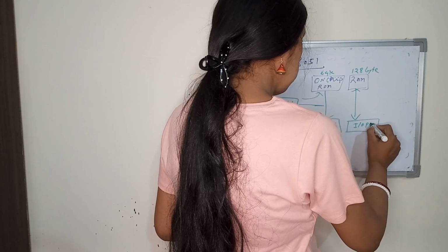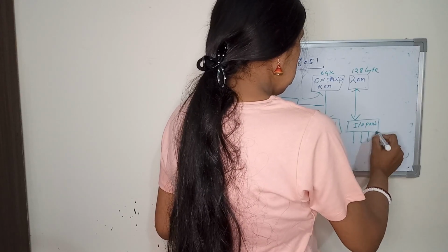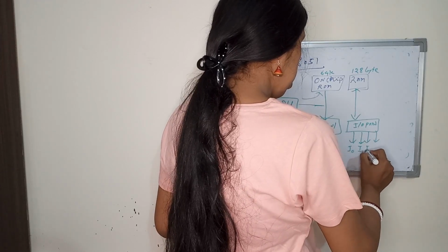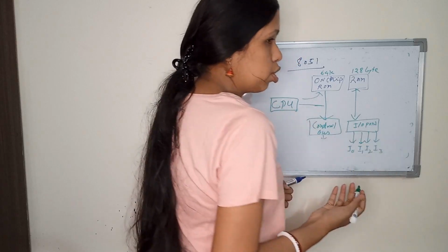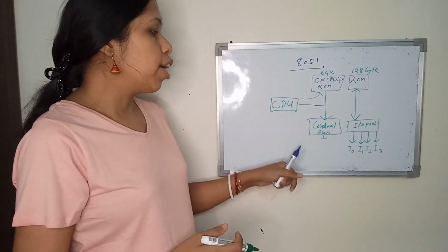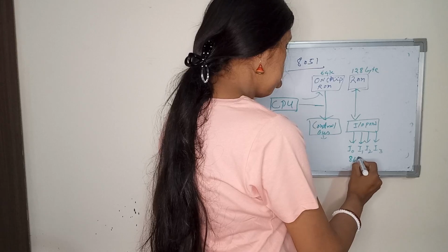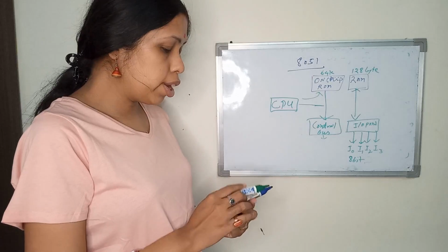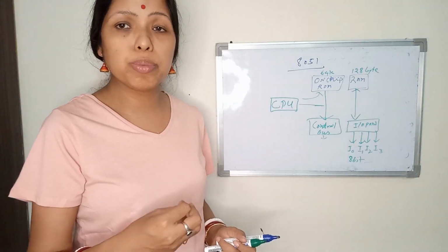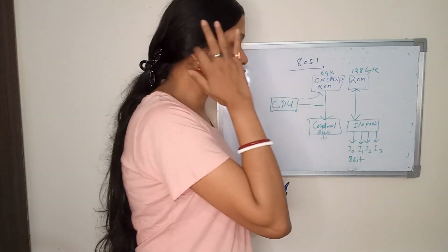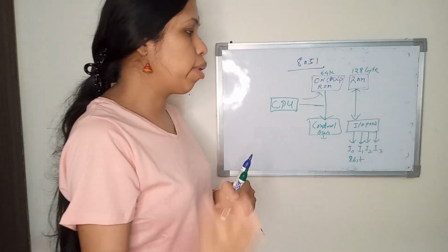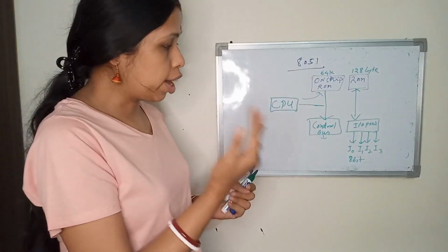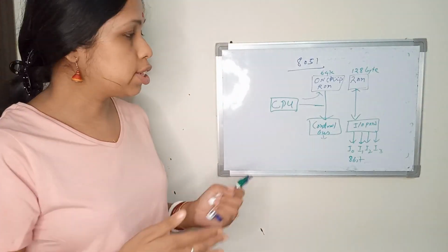IO port. P0, P1, P2, P3, or you can say port 0, port 1, port 2, port 3. IO port is 8-bit. In total there are 4 parallel 8-bit channels. So normally if you connect an external peripheral, it will be connected through these 4 channels. But some different functions are there between port 0, port 1, port 2 and port 3; this I will tell later.